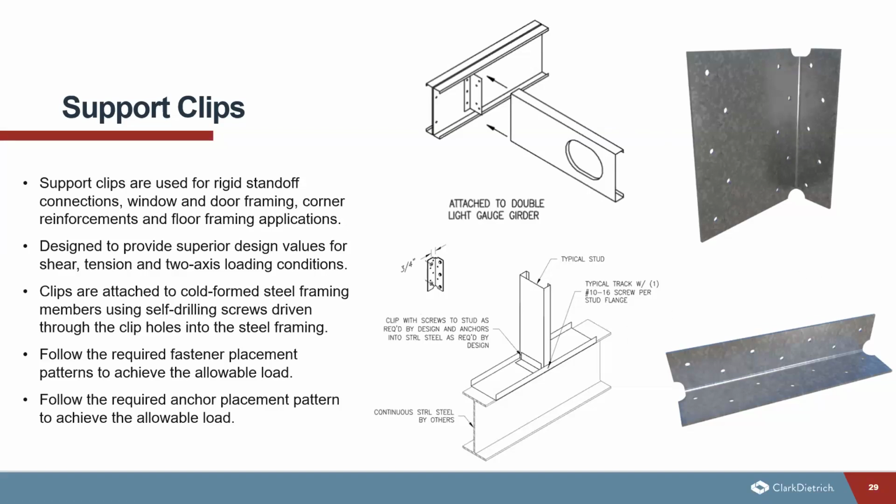Again, looking at these types of connectors, I would say 10, 15, 20 years ago, most of these connectors were just unpunched angle or track that was on site that they would cut. And now there is a whole market just for support clips that have tested and designed values to make it easier and the structure more sound.